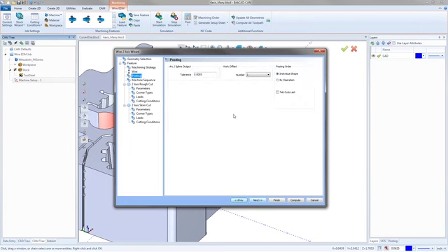Right here's the posting tab. So you have your pretty much just tolerances. This is the same kind of tolerance you're going to come across with just about any feature. 2-axis and lathe also have tolerances in them. They're just inside of the settings, inside file. So if you go to file and then you go down to either the settings part or settings default, they're on that page where you set up the tolerances. The wire EDM and the 3-axis milling give you the ability to set up the tolerance. So you can change the tolerance as you go through the features. So for the most part, I'm going to leave it right there.